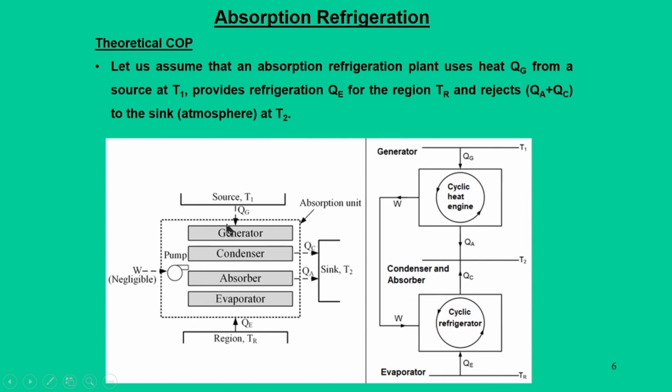Now, let us talk about some theoretical aspects. So, these particular things can be integrated in a manner that we will be able to find the thermodynamic estimates of COP for this kind of vapor absorption system.